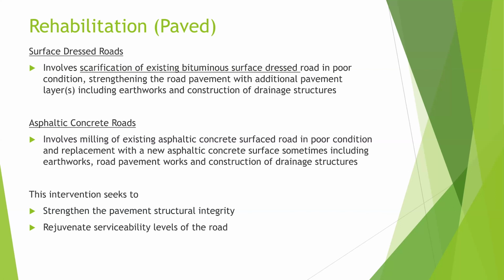Now, in all these cases, you need to scarify the existing bituminous surface dress. That is for the surface dress roads, the one which is in poor condition. You strengthen the road base with additional pavement layers, including earthworks and construction of drainage structures. So the partial reconstruction we talked about earlier didn't include the earthworks and the concrete works.